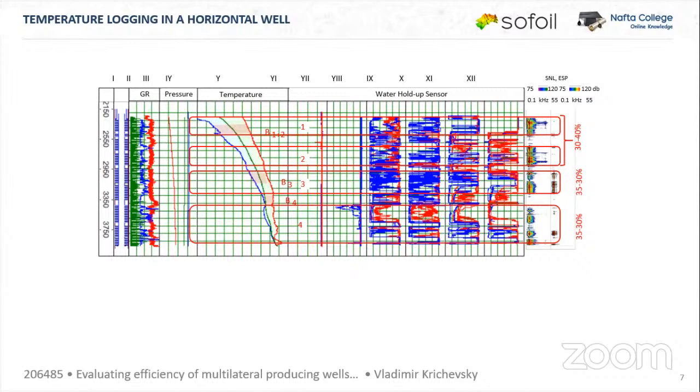All right, so again, this is a conventional production logging where we just put the gauge in a borehole, run it up and down several times, measure the static, then start producing, then shut it off, run several additional measurements. So it's a conventional way of doing it. So what is different with the DTS technology?